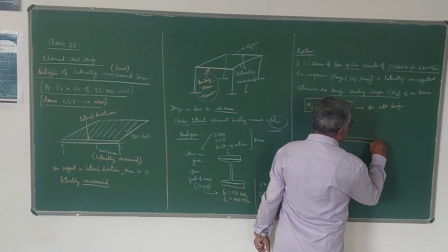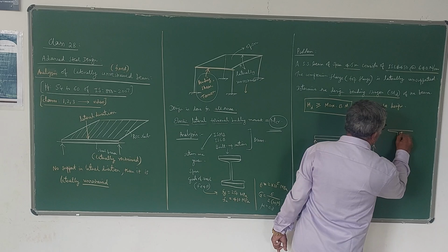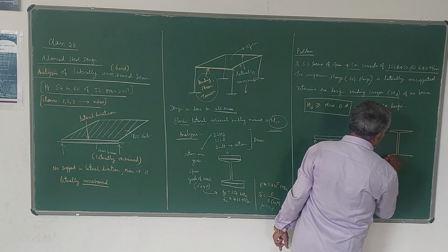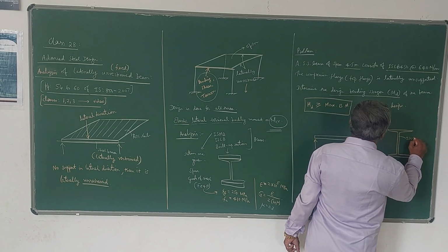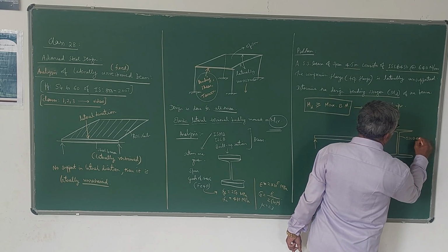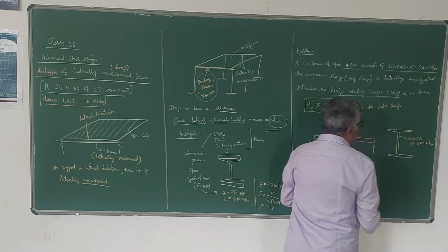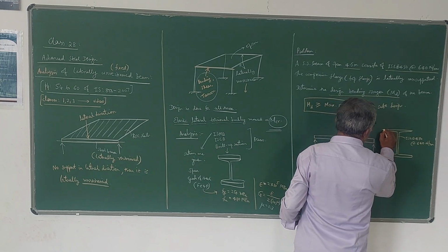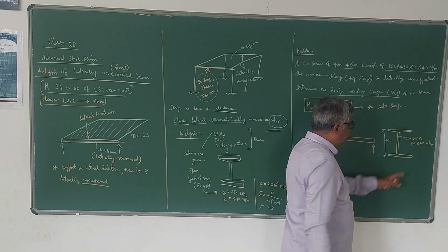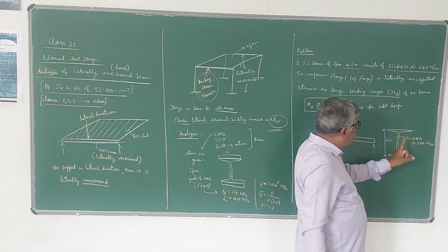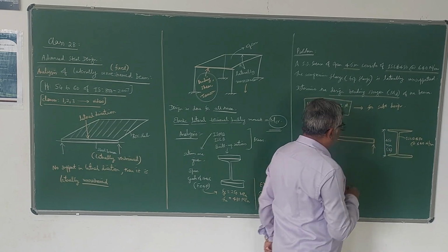Now we have to compute the capacity of this. What is the bending capacity? Design bending strength, you can say. This is your ISLB 450 at 640 Newton per meter. Please note that this overall depth is 450. Always steel sections are specified with the depth. This 450 mm is the overall depth, given by small h.